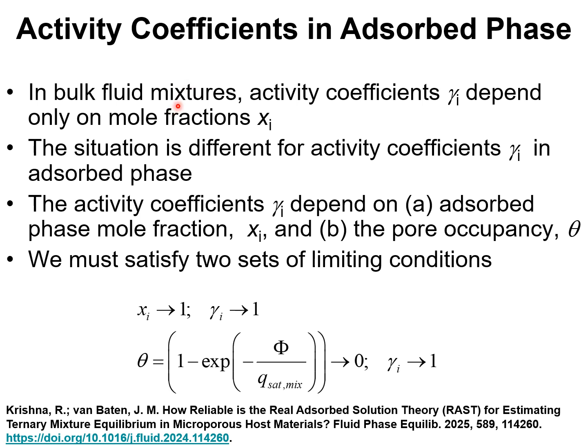In bulk fluid mixtures, the activity coefficients depend on the mixture compositions, say mole fractions xi. The situation is different for activity coefficients in the adsorbed phase within microporous materials. In this case, the activity coefficients of any component i depend not only on the adsorbed phase mole fraction xi, but also on the pore occupancy.